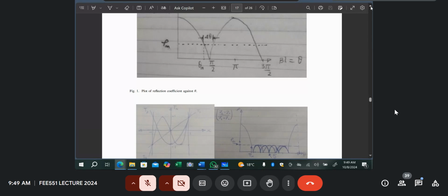But in this case, we are applying it in a scenario where whatever it ends up vanishing is good for us. So what looks like a disadvantage on the one side is actually an advantage on this side, because now we are applying it in a system where the reflection coefficient is our outcome, and we would like to reduce it. So the vanishing behavior becomes a positive thing, isn't it?